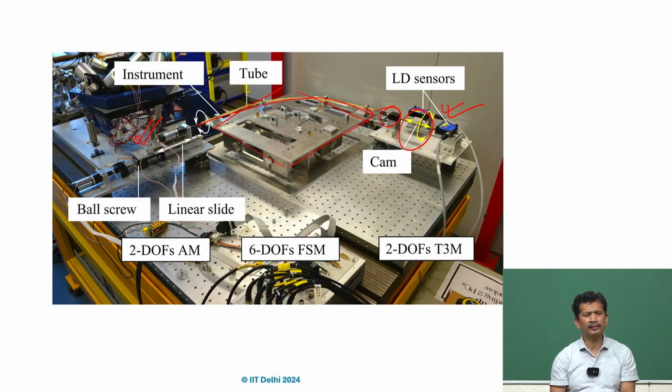It is not very big, just 1 millimeter diameter, and I think about 30 millimeter length, and it can take a very good load. Of course, if it comes under compression, we have to be aware of the critical buckling load.